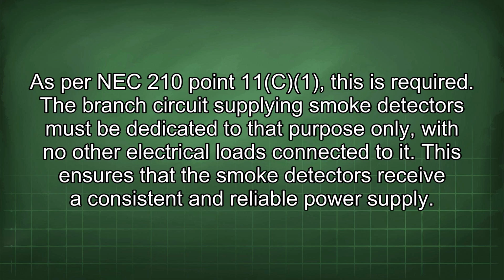The branch circuit supplying smoke detectors must be dedicated to that purpose only, with no other electrical loads connected to it. This ensures that the smoke detectors receive a consistent and reliable power supply.